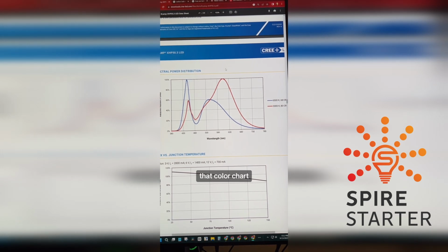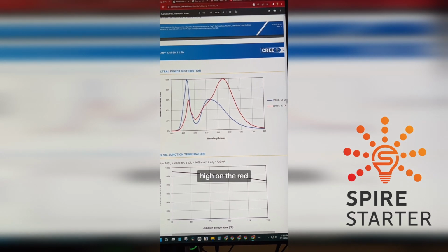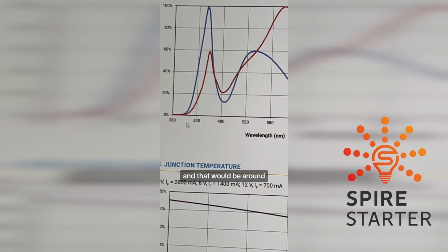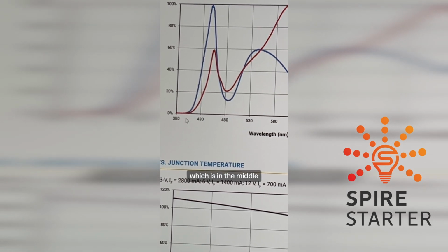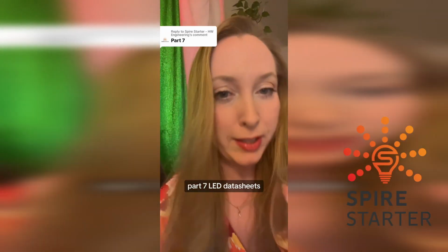As we saw on that color chart, the more red something has, the lower the color temperature. And so this is high on the red side of the spectrum, and that's the 3000K. And then as we get cooler white, the 6500K, you'll see that has a big spike at the blue side, and it's a lot lower at the red side of the spectrum. I got a question earlier about whether white LEDs emit UV light, and that would be around 400 nanometers or less, which is in the middle here. So really barely any at all. Part 7, LED datasheets. We can get through it.